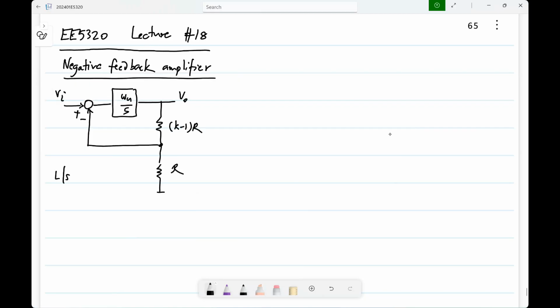In this, the loop gain is with omega u loop being omega u by k. This exact relationship, how omega u loop is related to the components in the circuit, depends on the exact circuit. But the loop gain is this integral.